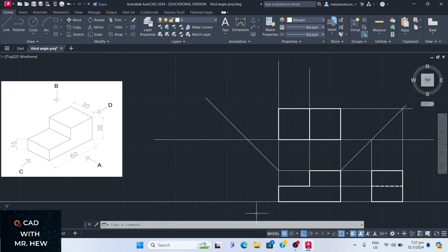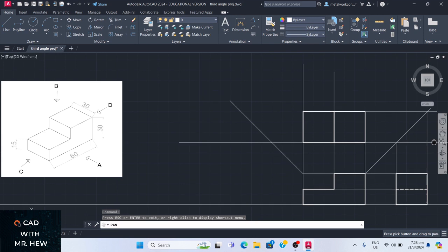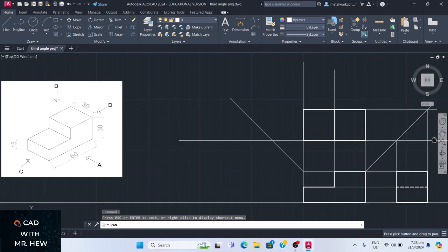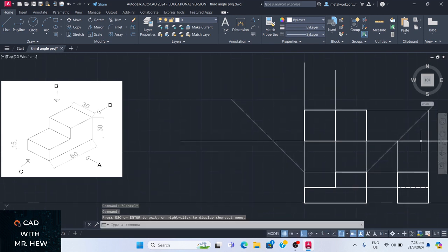We're going to draw the next one over here. All right. So here we have the plan view. We want to complete the other end elevation on the other side, because in today's video we are drawing two end elevations. All right. So we're going to draw a line from this point to transfer the width to the 45-degree line.